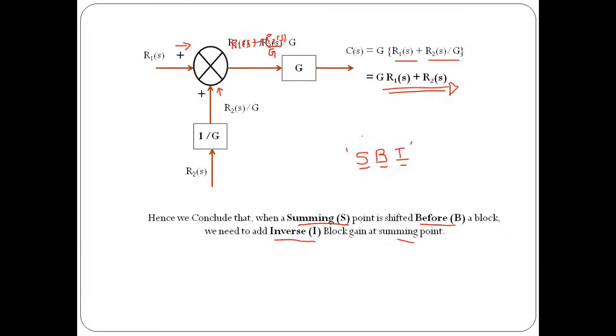So you have to remember that whenever you shift a summing point before a block, you need to add the inverse block gain. That's it.